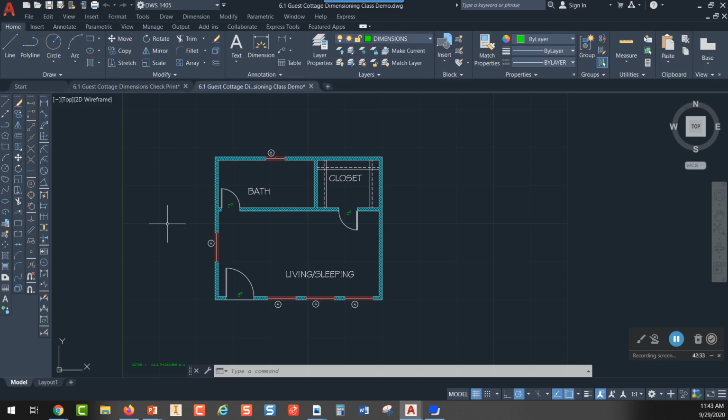All those styles are going to be set up in the dimension style. So then when you turn to page 316, you actually get your step 1, step 2, and in step 3, it says to create a dimensions layer. So we're going to put these on the dimensions layer, and so you'll want to make a dimensions layer. And I think most of that's going to be covered in the video for how to put your dimensions on this.